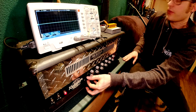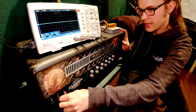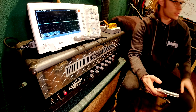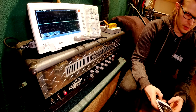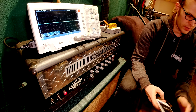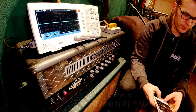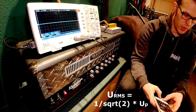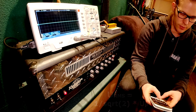And turn it down. Thank you very much for delivering us this nice sine wave. And now we have to calculate. I'm using the formula that we have drawn together. At first I'm using the factor, so I just put it on the calculator and show it to you. You can see the formula in here. I'm using 1 divided by square root of 2 multiplied with our U peak, which is 50 volts.